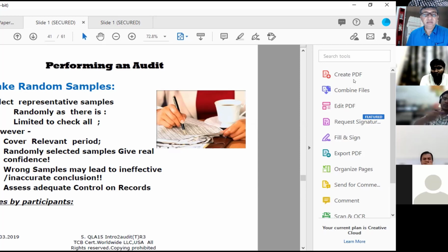But I will say that, show me the hydro test record and show me what was the requirement and who reviewed this. Whether the hydro test was done in accordance with the requirement, whether you are maintaining pressure chart, where you are maintaining the pressure gauge calibration, what kind of record and what kind of water you have used, what was requirement by the standards. All those things I'm going to check, and finally I will conclude that yes, this item has been manufactured in accordance with the customer requirement. I have seen evidence of entire process from beginning to end.